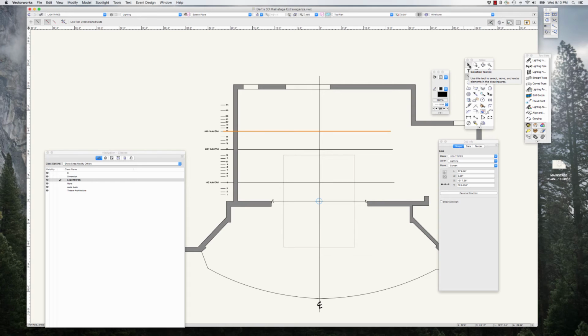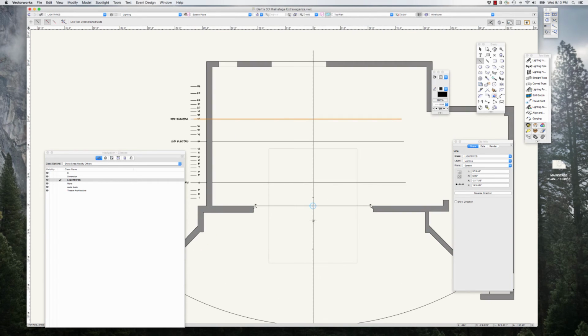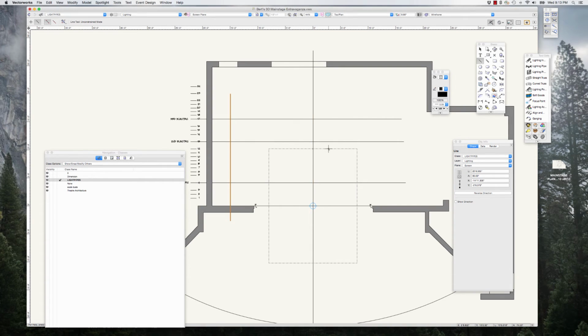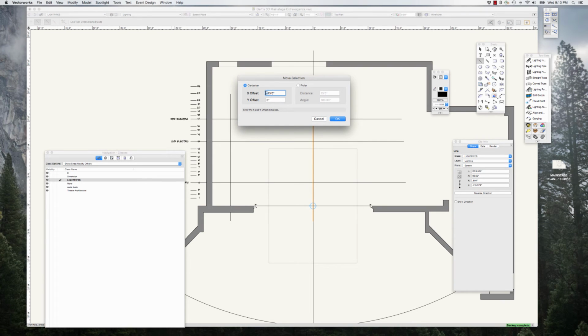Those of you who know the theater know that actually all of the pipes are different lengths. It's just silly, but the average is 30 feet. So they also are not really centered, but for our purposes here, I'm just going to center 30 feet pipes on the center line because that's what they should be, even though they're not. So I'm going to draw a line here and then modify, move minus 15 feet, 15 feet, 0 inches, and then we'll do another one, and if I move positive 15 feet.